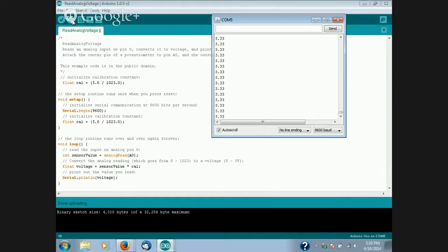But then, so that humans can actually interact with it, you usually represent the data as ASCII characters, because if you just feed raw numbers to the screen, they will come up as ASCII characters, because that's what screens do. So you take the time to convert your number into a character representation, and that's what this serial print is doing. It is taking a numerical binary value, voltage, and turning it into characters.